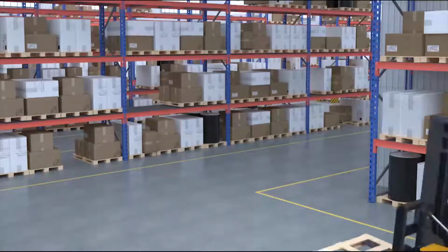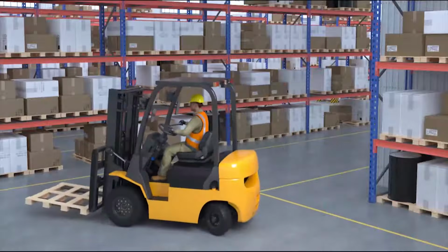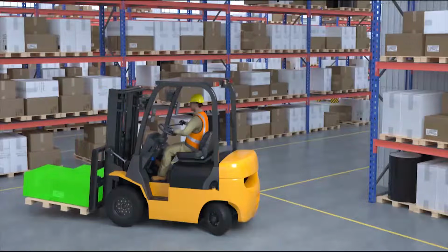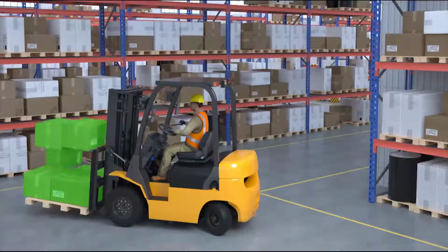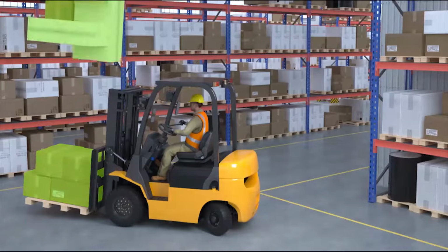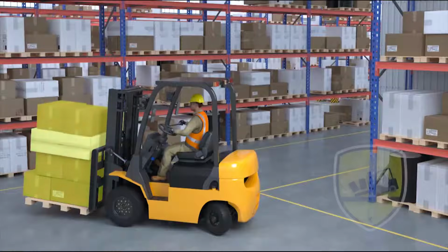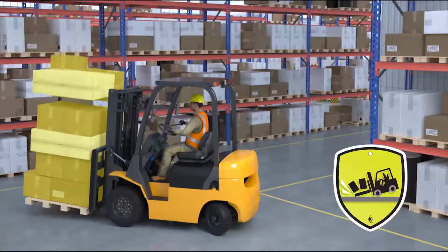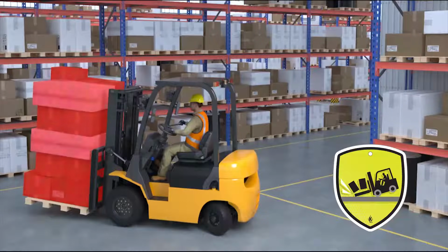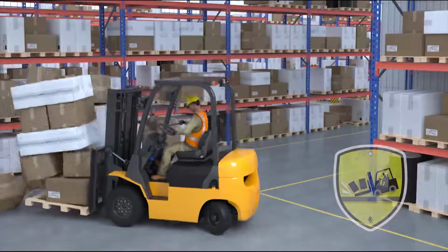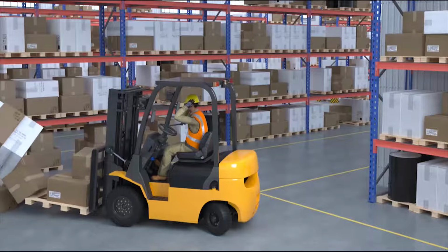Forklifts are actually much heavier than cars. They're made that way to counterbalance the loads carried up front. As a forklift operator, you need to constantly think about balance in order to keep your unit from tipping. Think of a loaded forklift like you would a teeter-totter. If there's too much weight on the forks or attachments, it's going to tip.